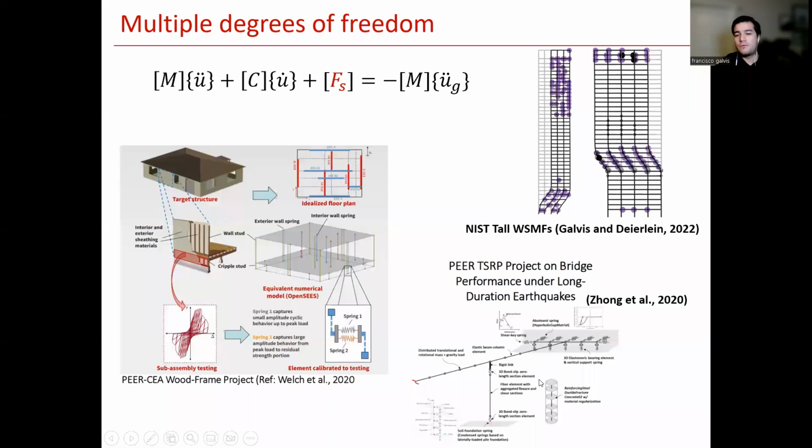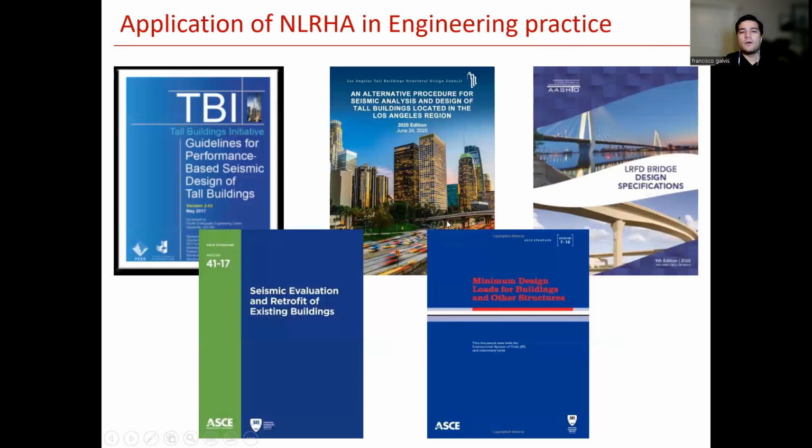Here is another example down here with a bridge, where we're trying to simulate the nonlinear response of the bridge, including nonlinear springs on the abutments to capture the response of the backfill soil when there is vibration and pounding. Also the nonlinear response of the columns and the deck and all that. And then here on the top right is an example of nonlinear response of high-rise buildings that can have damages and fractures and nonlinear response on the beams, columns, splices, and panel zones, and all the different elements that conform the structural system.